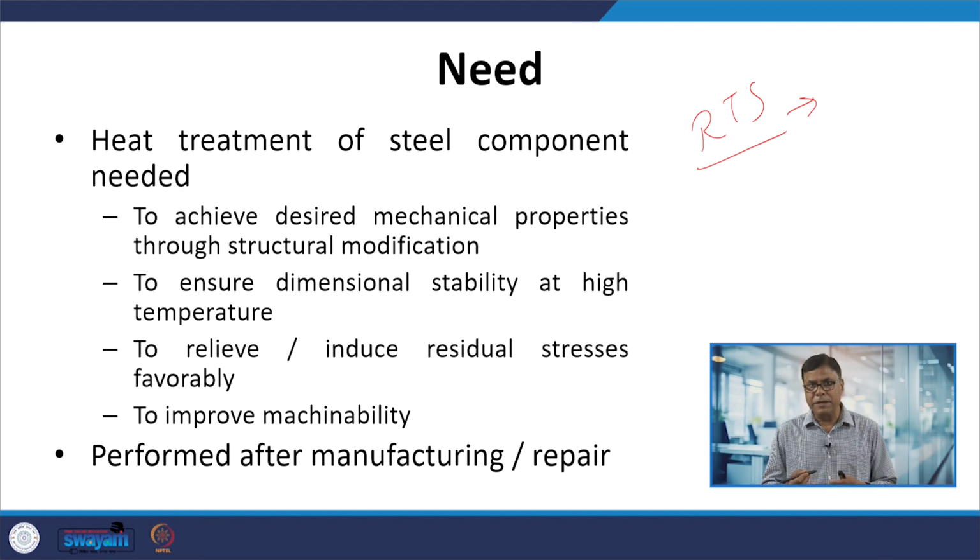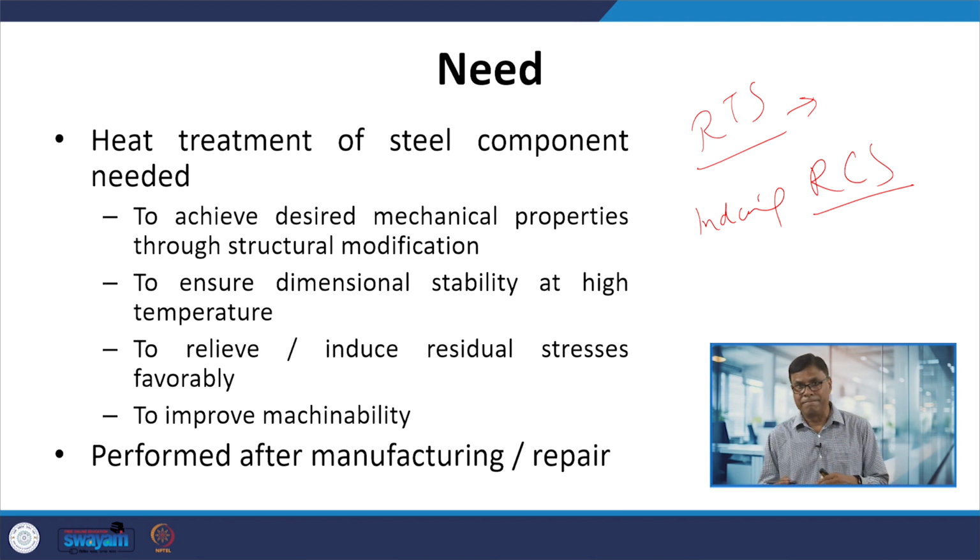So, efforts are made to neutralize the effect of these residual stresses by inducing residual compressive stresses. If residual tensile stresses have been developed, their magnitude is reduced through heat treatment. That is called a stress relieving treatment.